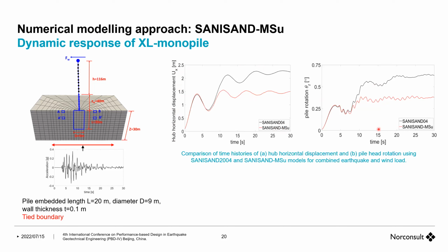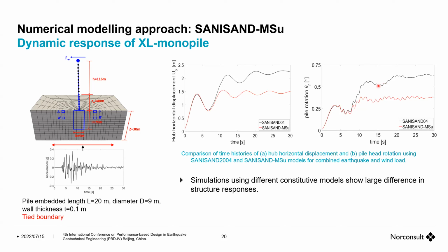This is as a function of time, and as the shaking continues, you will see that there is accumulation of rotation, and the two motions follow each other. But as expected, this is not a surprise, the models of 2004 show more quick development of liquefaction, therefore larger rotation. So this is almost expected, but pretty much similar trend.